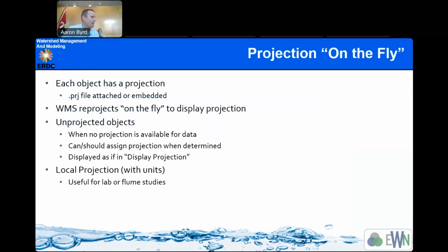Yeah, and if you bring in all your data and it doesn't work, go back and check the projection. It's like the first thing. You pull in all your data, just go check your projection and make sure it's where you think it is. If your data are 100 feet apart when you look at them, then you've got your projection wrong. So this is really critical.